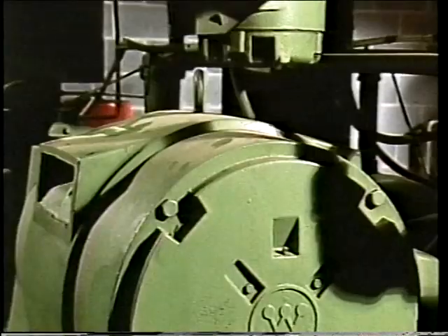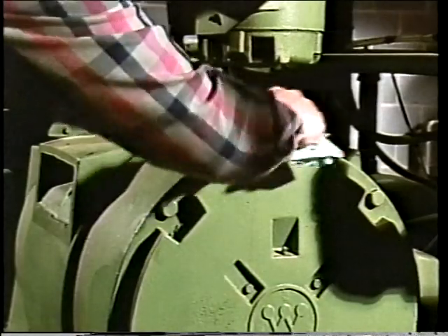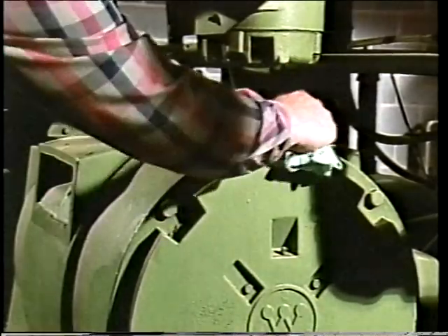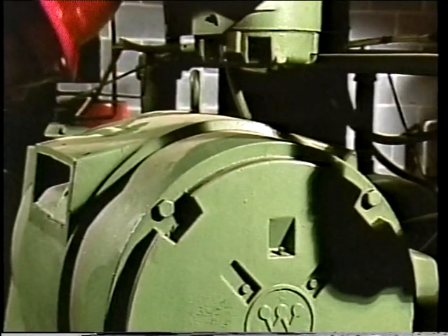Since contact pickups can be moved from component to component during vibration testing, they must be mounted properly to ensure that the information they provide is accurate. This includes how the contact pickup is attached to the machine that it's monitoring and where the pickup is positioned. For example, the pickup should always be attached to a clean, smooth surface that is free of any material that could interfere with the contact between the pickup and the machine.